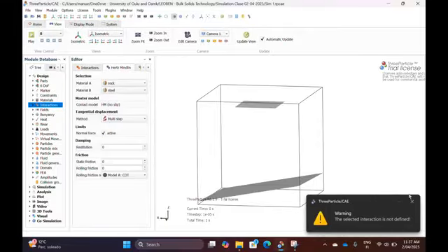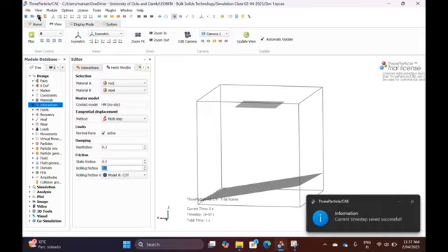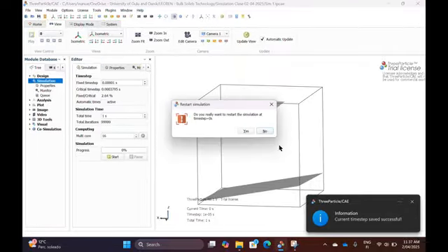And we have some friction parameters, also between 0 and 1. And that should actually be calibrated. But we start with some values that I know. 0.3 works quite well, and rolling friction a little bit less. Static should always be a little more than dynamic. It also says that to you if you did not do so. So let's start with some values. And again, save. And now, if we go to simulation again, and we start, particles should fall out of the ceiling at some point at least.